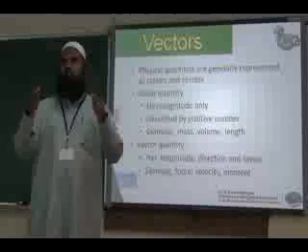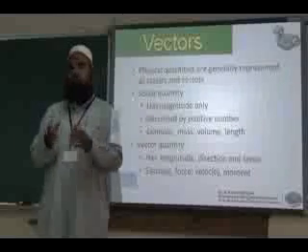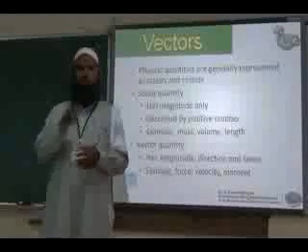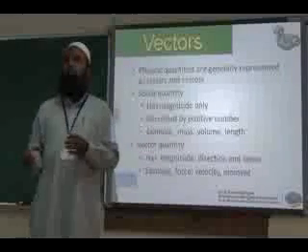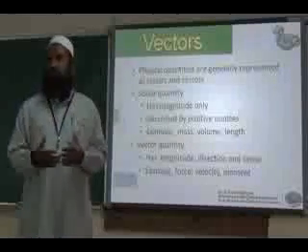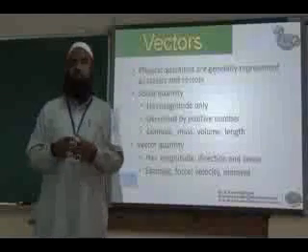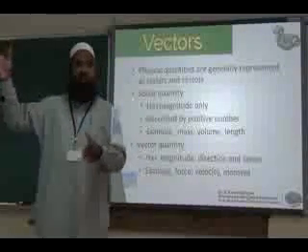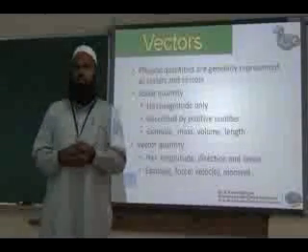I have given you an example also: a hook pulled by two cables. In order to check whether the hook can withstand the load, we have to find the net force acting on the hook. For that, we apply the vector addition concept. We find the net force, then the net stress acting on the hook. From the stress, we check whether it is within the material's safe stress, and then we say the hook is okay with the load. So the basic vector concepts are used until we design a component. That is why vector quantity is very important.